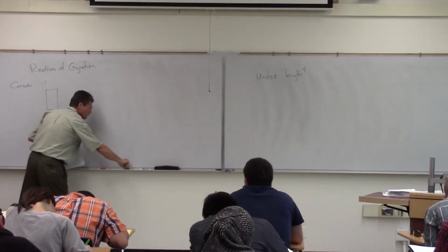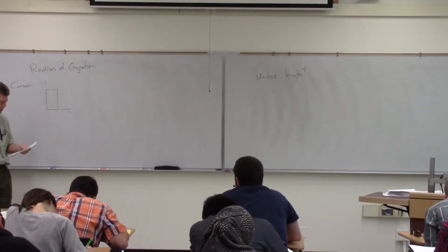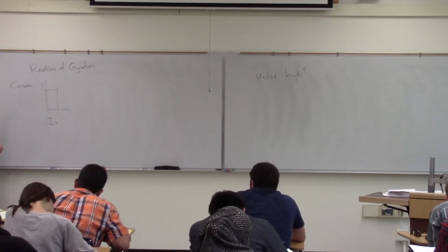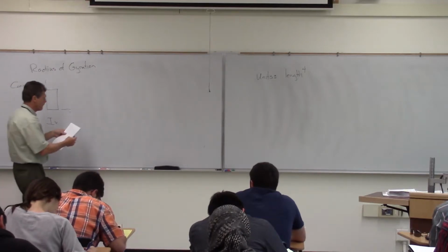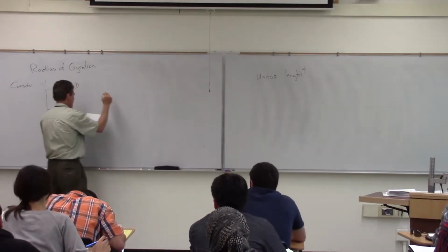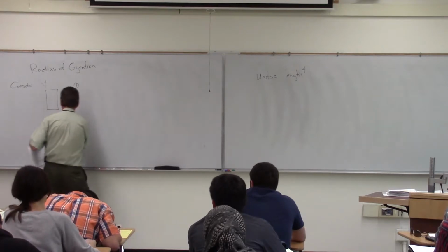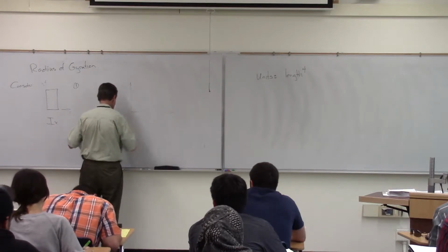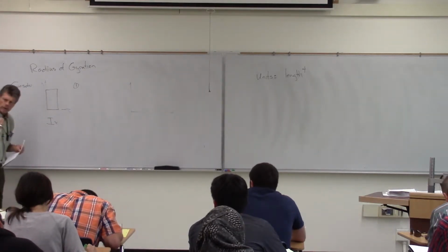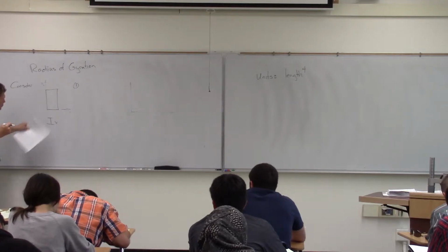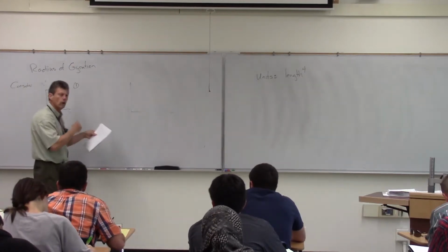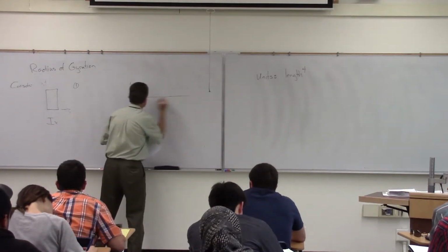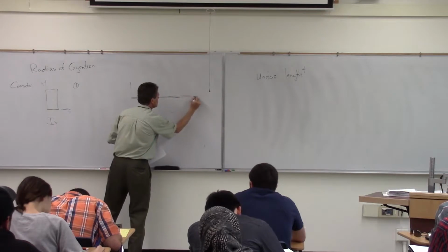Okay, consider the fact that we can take a rectangular section and calculate an Ix for that section. What radius of gyration basically says is that we're going to take that same section there, and I want to keep the area the same, but I want to create the same Ix by simply moving all of that material off into one little thin infinitesimal strip here.